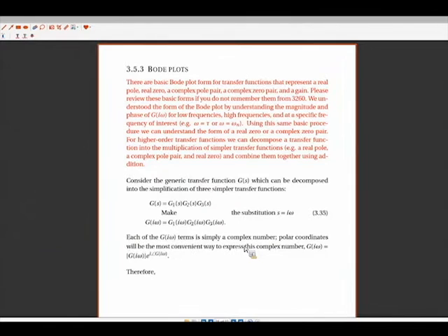And so it is, from a pedagogical point of view, much better if you actually know how all these individual components add together. So we're actually going to be bending the Bode plot of integrated systems by putting poles and zeros in line with the system to make the Bode plot bend. And for you to understand how to do that, it's best if you go through the arduous process of doing it by hand. And so we will be doing that.